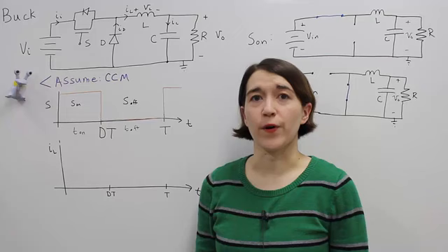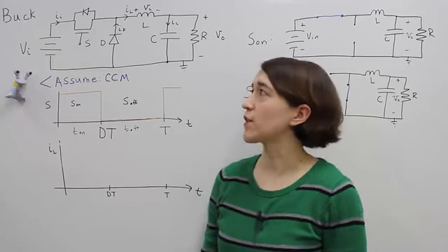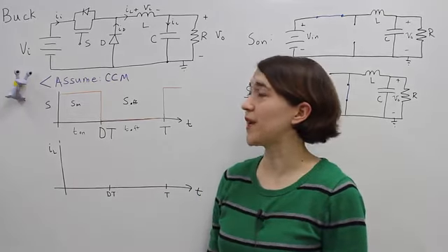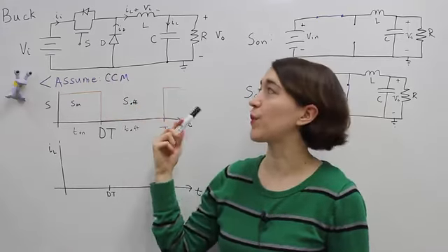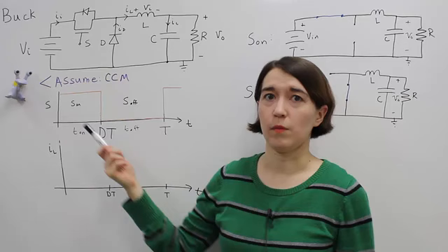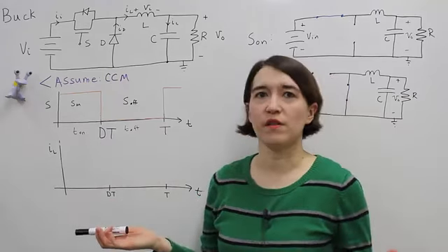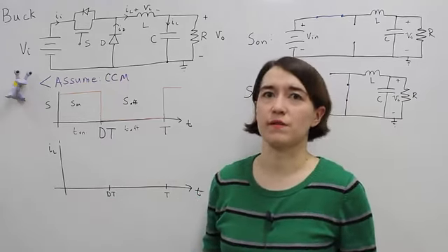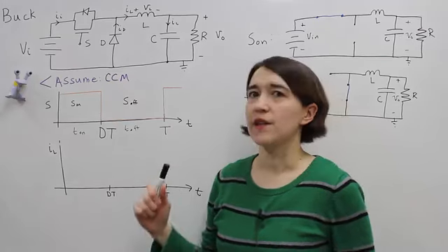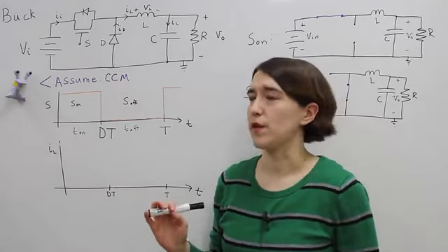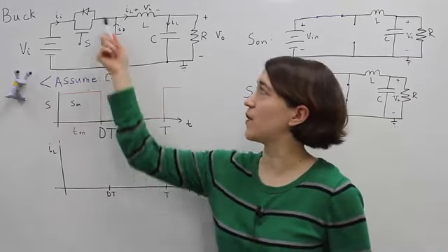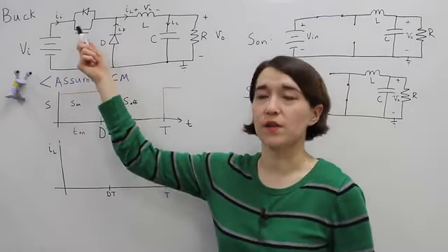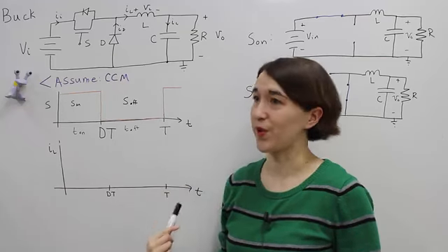So we mentioned before that the buck converter has a relationship between the input and output voltage. We know that the output voltage will be lower than the input voltage, but how do we know, and what determines this ratio? The answer is that we control the duty ratio, the time that we are in the on state for this switch relative to the total period.